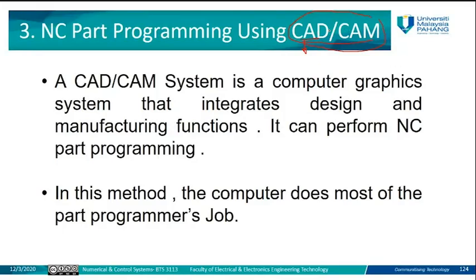Like the software that I shared with you, SolidWorks, or Fusion 360 with the CAM feature, and so on. All these types of software can do two parts of the work: draw or design the product using engineering drawing, either 2D or 3D, then generate the G code from these drawings. If you have a drawing of a square, you can generate a G code from this square.